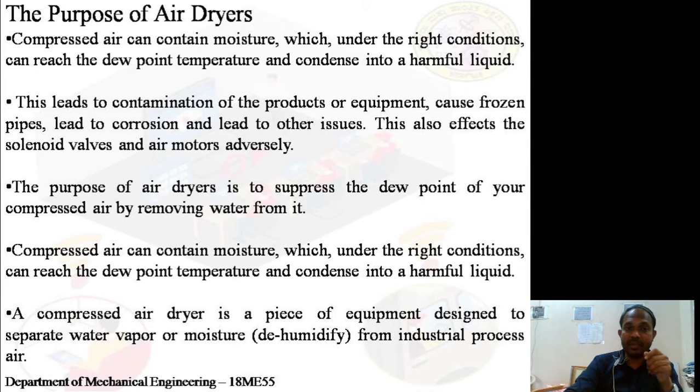That is the reason why we should always dry the air coming from the compressor before it enters the receiver. Once it reaches the receiver, it will mix with the previously stored pressurized air along with the fresh air, so it will damage the quality of the compressed air.